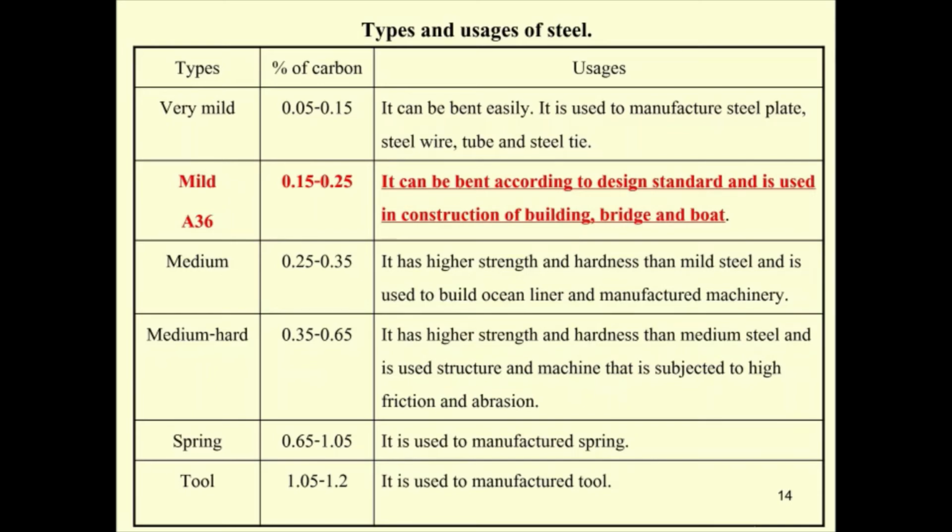Okay, this table shows you the typical usage of the steel. Mostly they follow the ASTM standard. We use mild steel, and for Thai TIS, you may use the grades specified as FE24 or FE30. That is going to be the typical mild steel that we use in Thailand. So anyway, when you decide on it, you've got to take its mechanical properties and follow them closely.